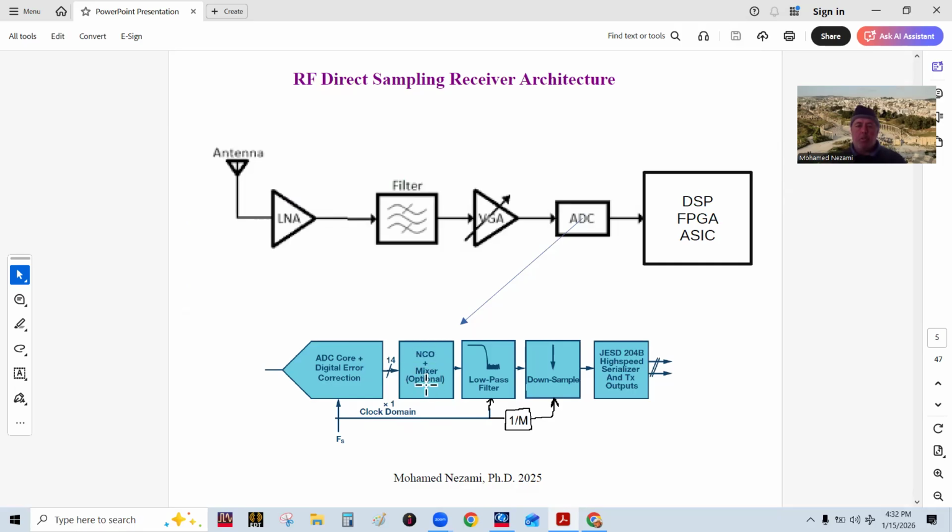Of course, it's a quadrature because this signal in here is complex. Or even if it's real, I mean, this is real, but we're going to make a complex out of it, and that's when we multiply it with an NCO using a numerical multiplier. Then of course we low pass that, because as soon as you do that, things will shift back close to the desired band, and then we're way oversampling relative to the bandwidth required, or the minimum number of samples per symbol.